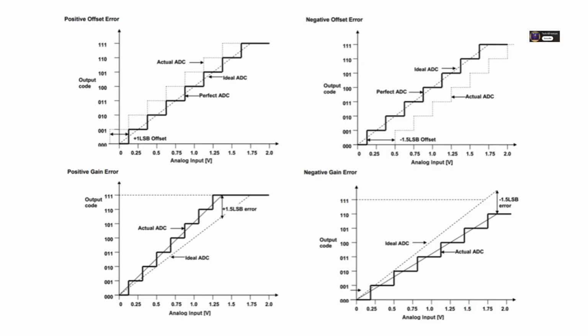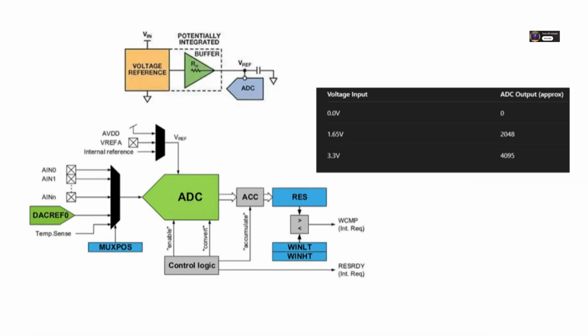All right. What about this reference voltage you mentioned? Ref. Hugely important. The reference voltage defines the absolute voltage range the ADC can measure. The ADC essentially maps 0 volts input to a digital output of 0, and it maps the ref voltage to the highest possible digital code, which is 2^n - 1 for an n-bit ADC. So for that 10-bit ADC with a 5-volt ref? Right. It maps the 0 to 5 volt input range to digital values from 0 all the way up to 1023. So if your sensor puts out, say, 6 volts, but your ref is set at 5 volts, that's a problem.